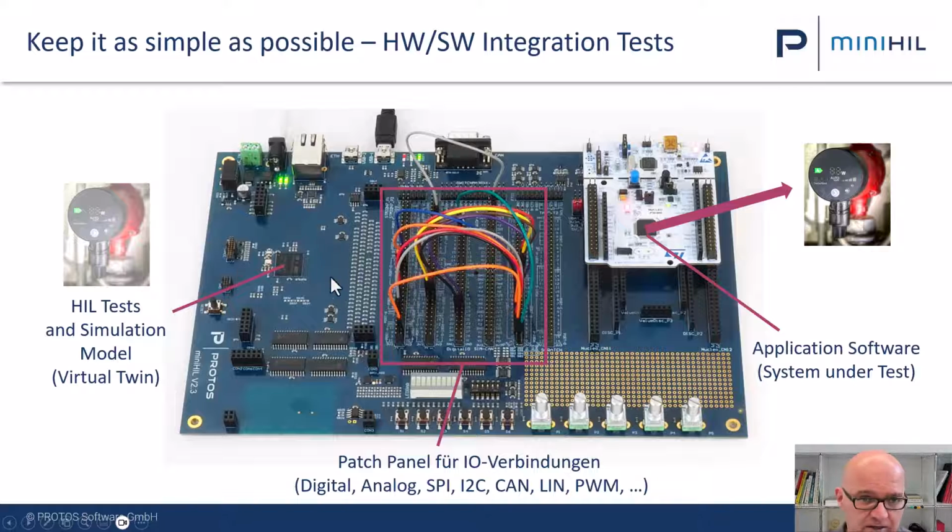So now on the side of my test system, I need three things. I need the drivers to be integrated for the signals. Then I need environment simulations to simulate the motor, the temperature, the battery, whatever your system is made of. Because if there is no simulation, you cannot run your system and test your system. And the last thing you need is test cases. The biggest effort goes into the environment simulation. Test cases are relatively simple to do if you have the right tools, but you need the environment simulation, and we also have the right tools for the environment simulation.